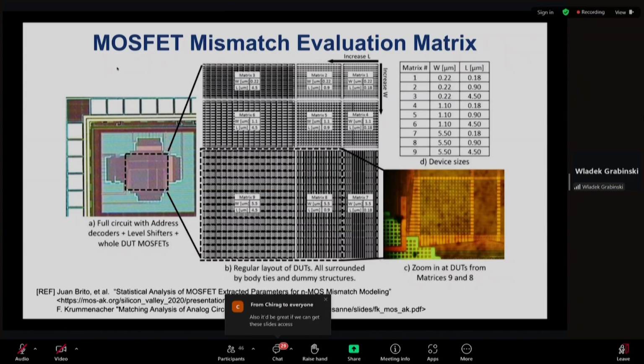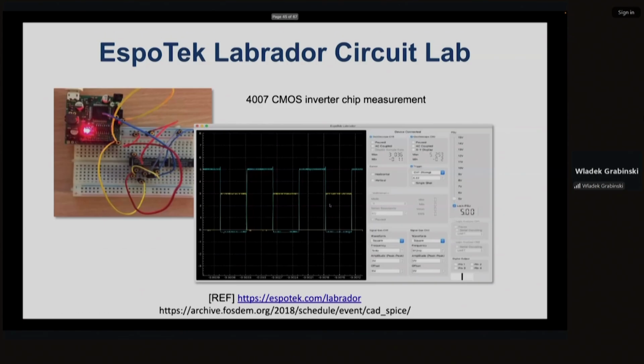As I mentioned, SPICE compact models are critical. So we are also supporting a dedicated test chip to analyze device performance, look at the device statistics, in particular the device matching, which is critical for analog transistor level design. We are about to implement a new test chip for, in this case, matching evaluation. Measurements are quite critical.